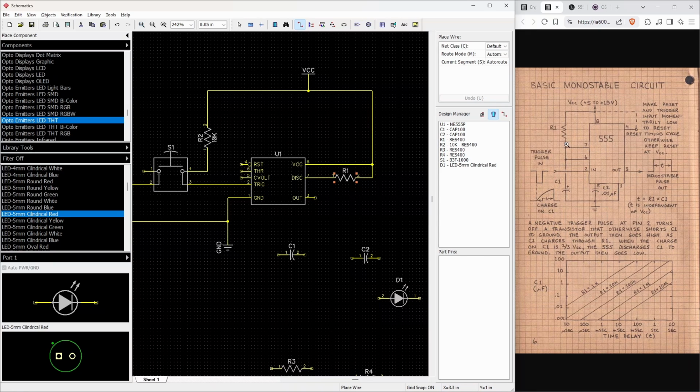Now, the other thing that pin 7 does is it goes to pin 6. So let's make that happen as well. Like I said, this is not a great arrangement for these pins, but it's not great to have a bunch of overlapping things. So I'll just make this go over here, down to pin 7. Now that's weird that it did that jumping thing, I don't normally see that. Maybe I don't want to do that. Not seeing the dot there shows me that those aren't connected to each other. Okay, so pin 7 goes to pin 6. It also goes to R1.